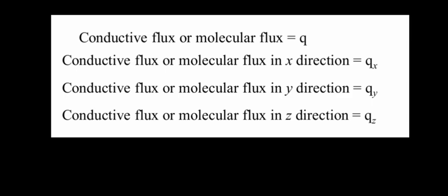Where T is the temperature, the proportionality constant is the thermal conductivity of the fluid. Therefore, the conductive heat flux vector Q represents the rate at which thermal energy is being transported through the fluid due to these molecular interactions driven by temperature differences. Even if the bulk fluid is not moving, heat can still be transferred from a hot part to a cold part through conduction.